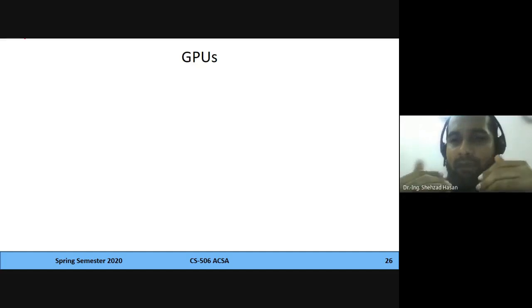In carry skip, this same example is going to give you only half of that delay, because it's going to skip most of those parts by propagating the carry earlier. This is the advantage. You just had to give one example, and that was enough. No one did that as well.